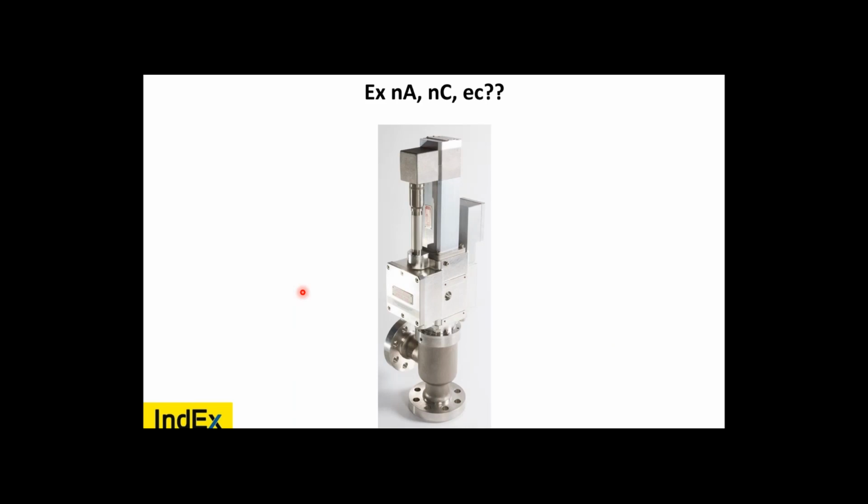Well, what is this? Looks like a pressure relief valve. So which Ex protection technique is it? Well, it's Ex nC. This one is the non-incendive, meaning it just has to be inside of a mechanical enclosure.